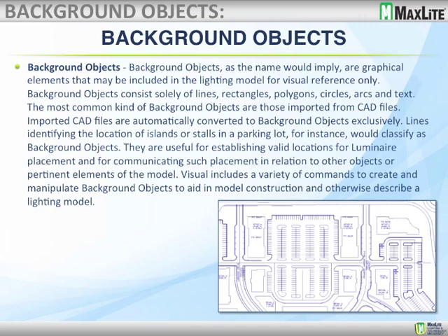Well, a lot of that is taken as obstructions. If you see, there are buildings within this parking area. There are buildings to the left and the right of parking stalls or drive lanes, etc. Those we have to put in, and a lot of times we assume a 30-foot height unless we're told otherwise for a lot of these buildings to make obstructions, because we know light does not bend. It goes in one direction, so we will not be able to put light directly through a building, we are able to obstruct that light.